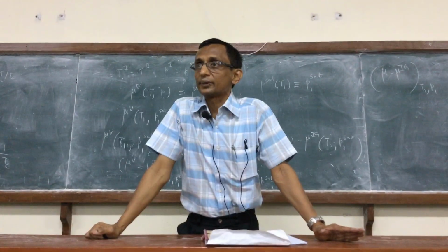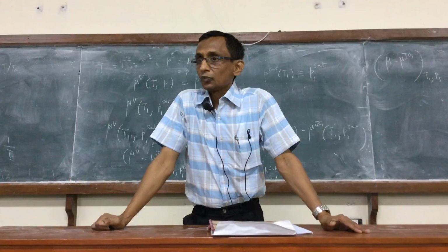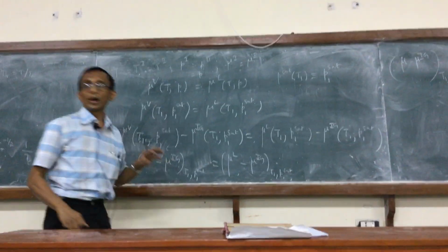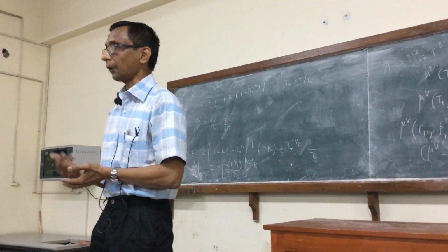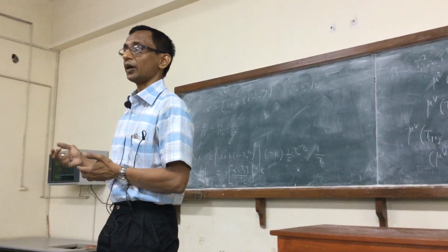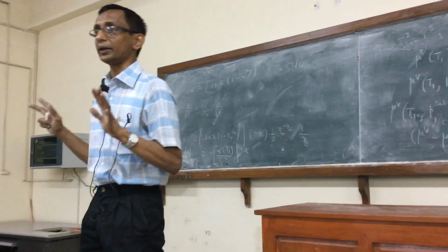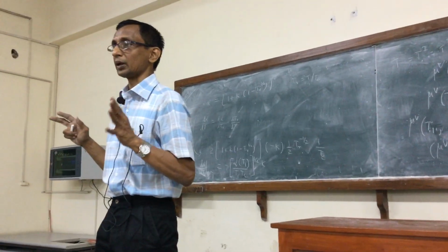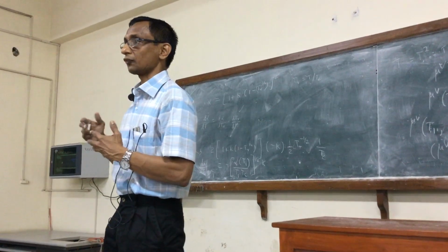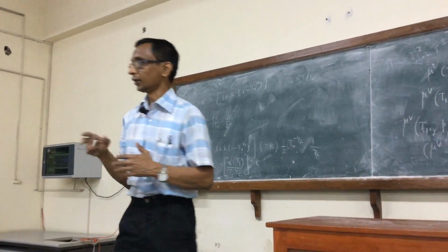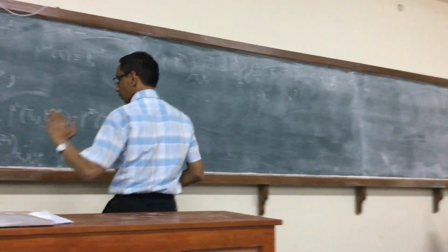There has to be some difference, right? The difference is obviously in the V1. So for the vapor phase, one has to substitute the specific volume of the vapor. For the liquid phase, one has to substitute the specific volume of the liquid. That's the only difference between the two formulas when applied to the liquid and vapor phase. So the temperature and pressure of the two phases are the same, right? So that is where the difference comes. So let me now write.